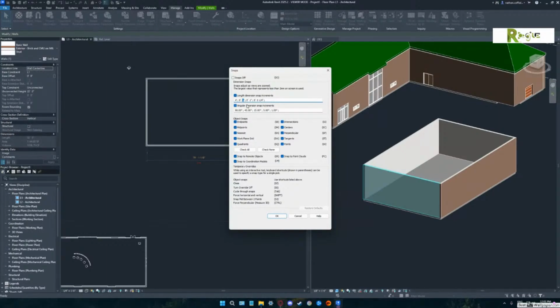That 4-inch, as opposed to a 6-inch, allows you, when you're drawing, to make your building what's called coursed, so you don't have to cut brick. So that's something I normally wait to tell people when we get to the manage tab, but I wanted you to understand that nudge factor. Does that make sense?